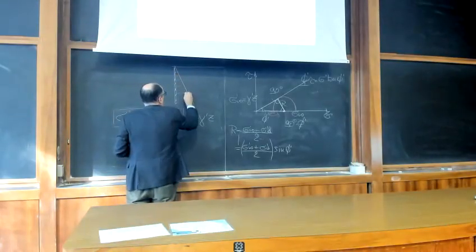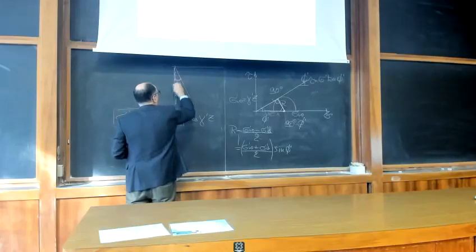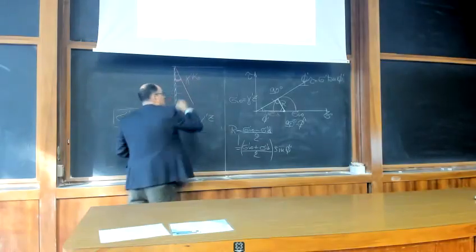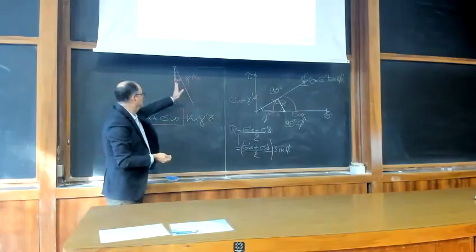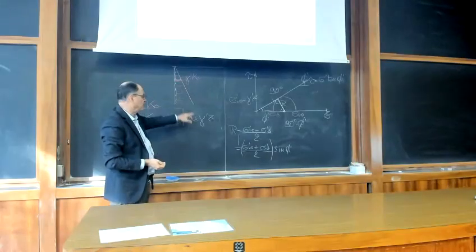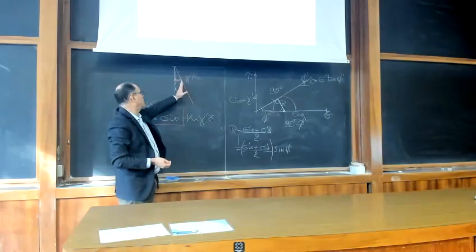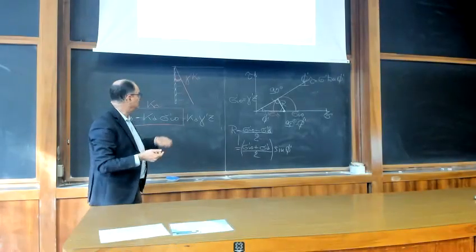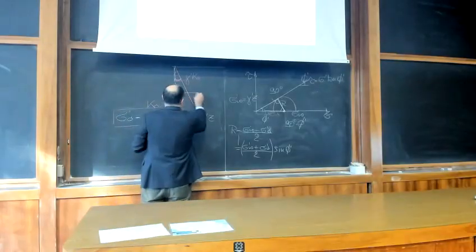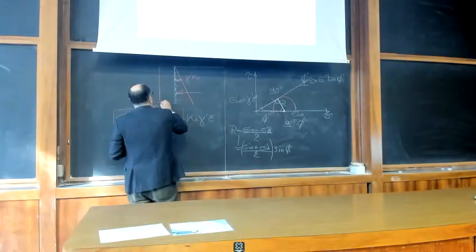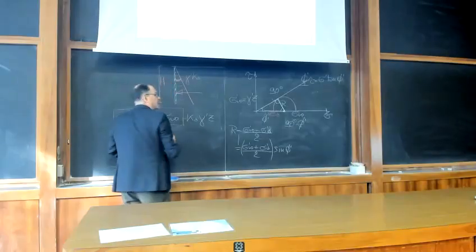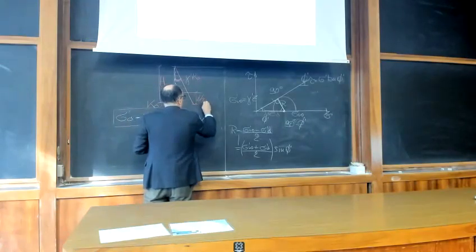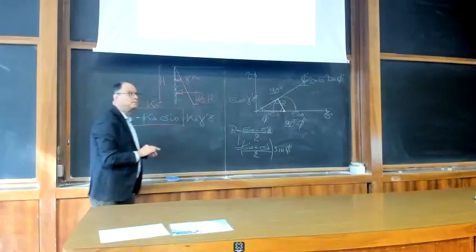So the slope of this line will be gamma dash times Ka. And being Ka less than 1, this is smaller than the vertical stress. But this is what acts against the wall, and this is why Rankine says the resultant of this is applied at 1/3 of the height h of your wall. This is 1/3 of h.